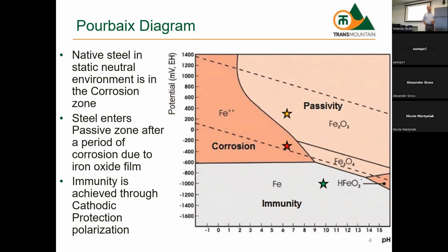Okay? So if you have a pipe or a structure that's buried in soil, the pH of the whole soil environment is not changing. It's only changing due to the chemical reactions that are occurring on the metal surface. So if you were to test the electrolyte, the soil or the water that's in direct contact with the metal surface, that pH is going to be higher. And that's due to the chemical reaction, which I'll show you in 2 slides.